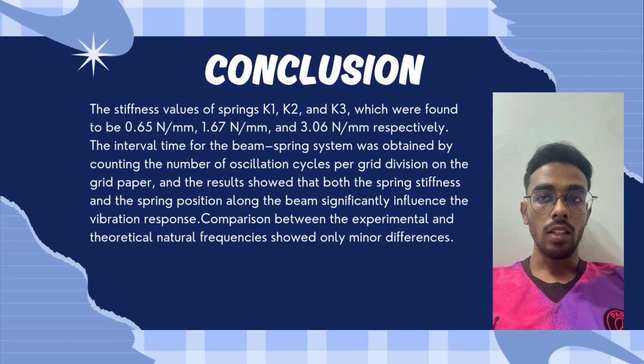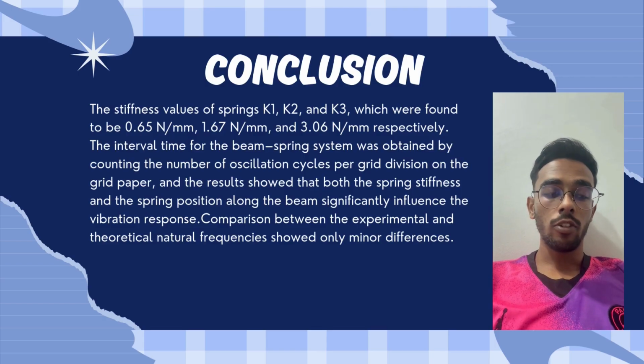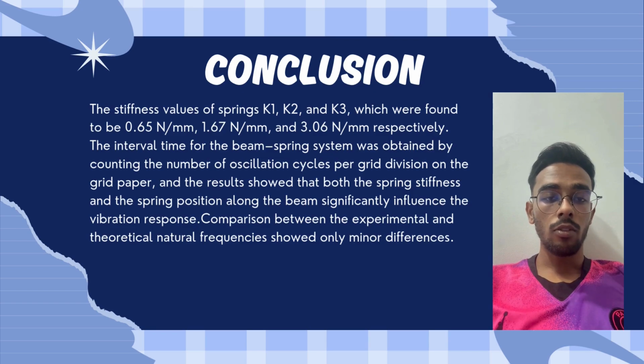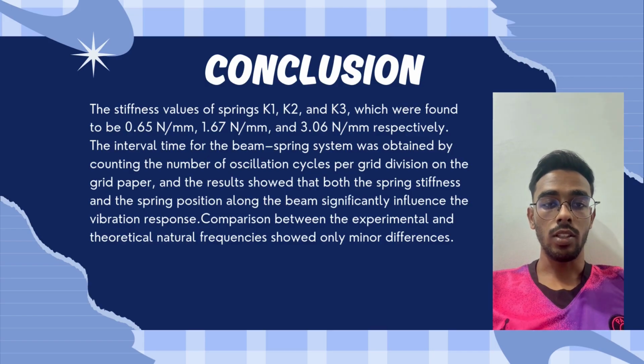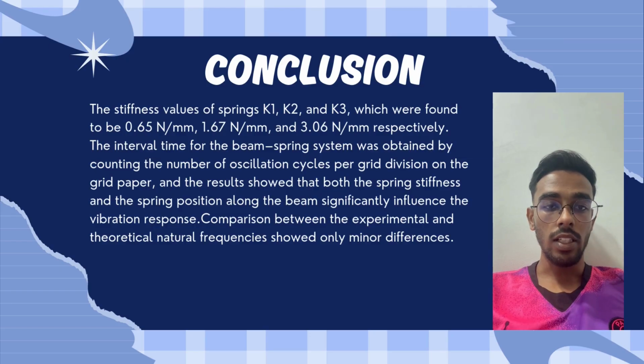These confirm that the springs with larger wire diameters exhibit higher stiffness. The interval time for the beam spring system was obtained by counting the number of oscillation cycles per grid division on the grid paper, and the results show that both the spring stiffness and the spring position along the beam significantly influence the vibration response.